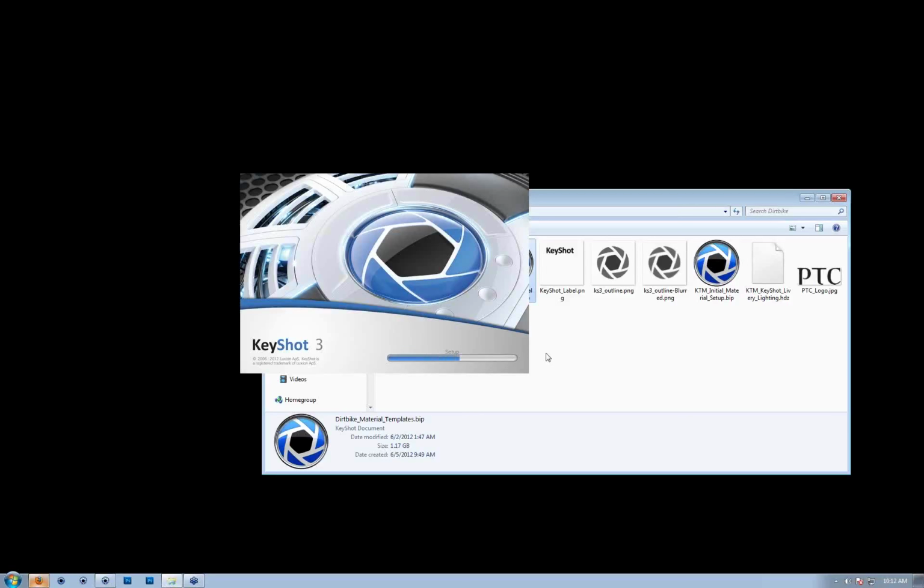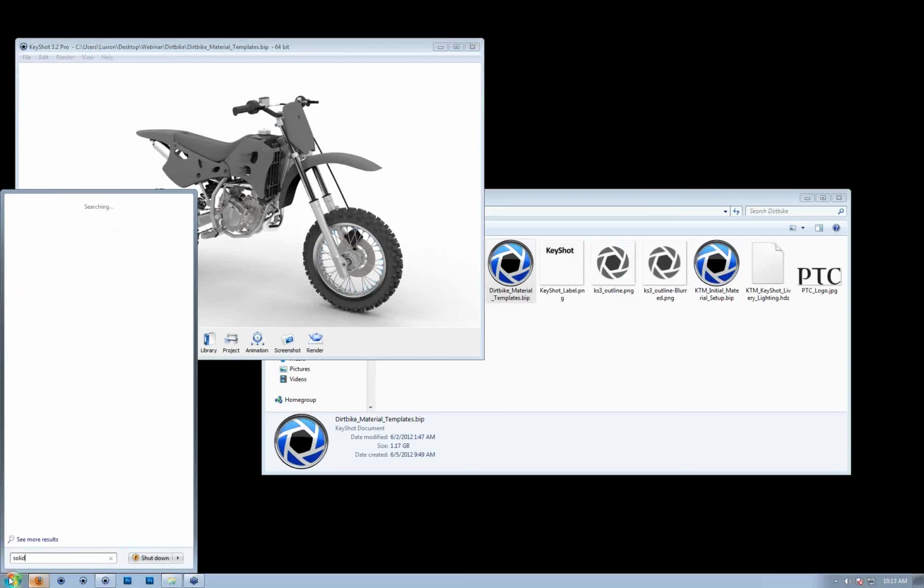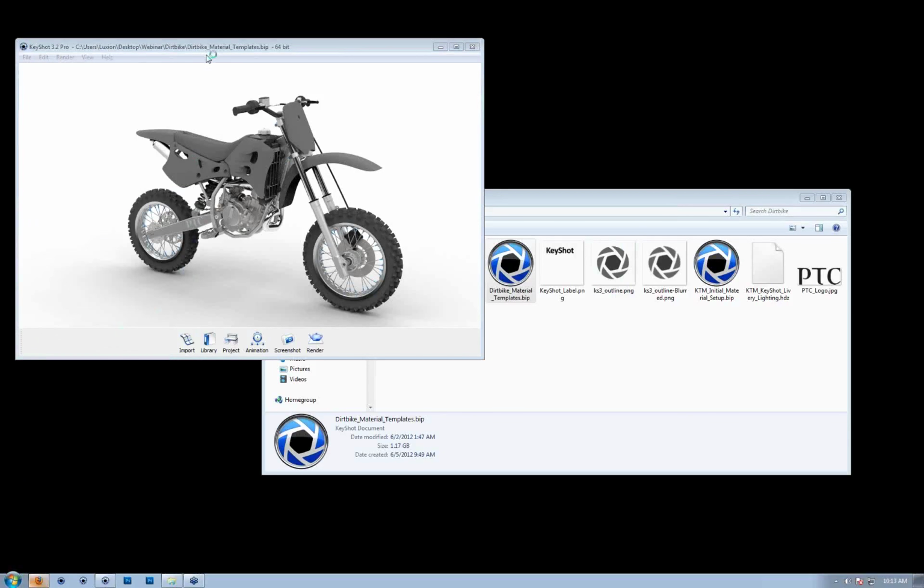Is material callout applied at the native CAD level? What I guess you're asking about is, is it detecting from the CAD level the name of the materials, and if that's what you mean, different CAD software interact with it differently. In your case, you use SolidWorks mostly, so what you're going to see out of SolidWorks are names of materials called color, colon, some other name, then 3 numbers describing the RGB. So for that, what you can actually do, and let me just take a little detour here.